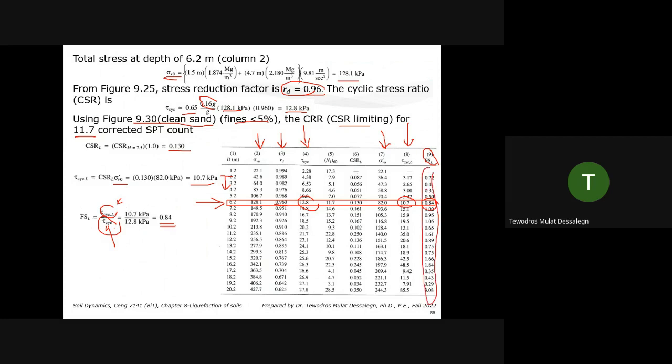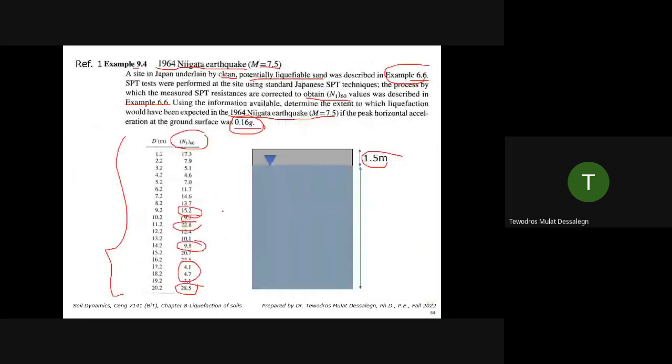Your factor of safety is 0.72, 0.35, in some cases more than 1, 1.66 doesn't liquefy, but see this soft layer also, 0.29, 0.43, 0.35. So in my experience, if you see corrected blow counts less than around 12, less than 10, expect liquefaction if it's a saturated area. But it depends on the depths also, because effective stress matters. The initial stress condition matters.